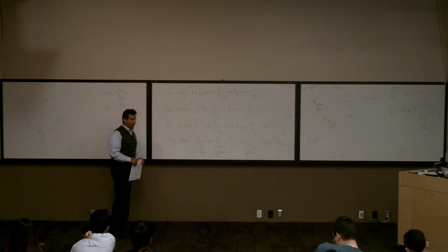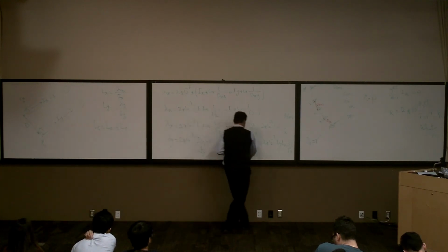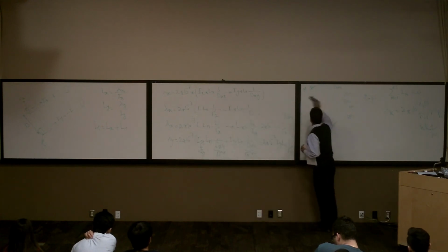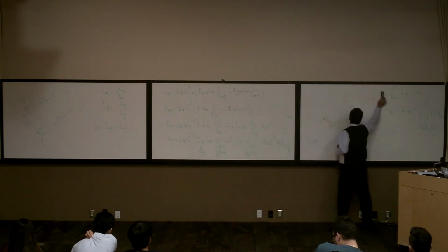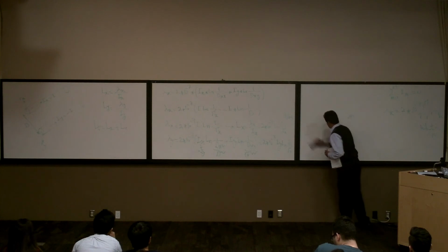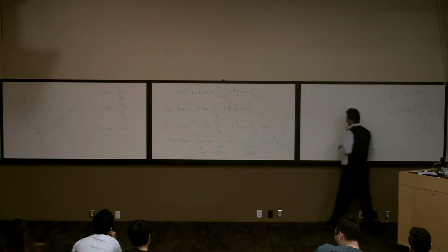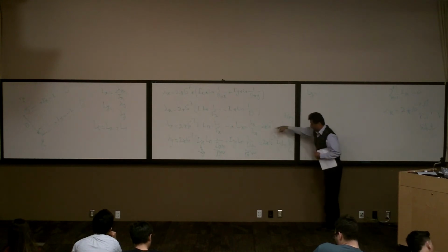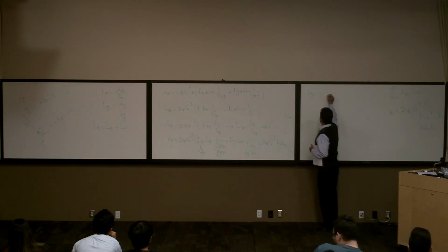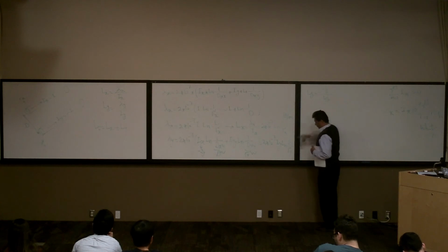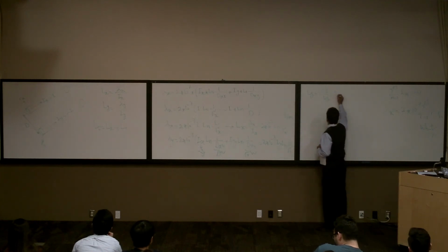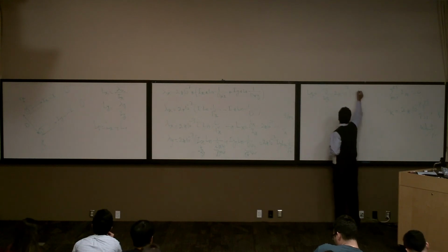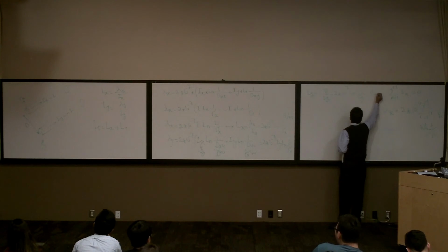How much is the Ly? It is lambda y divided by Iy, so Iy is going to cancel. It's going to be 2 times 10 to the power of minus 7 ln of d over r prime y, Henry per meter.